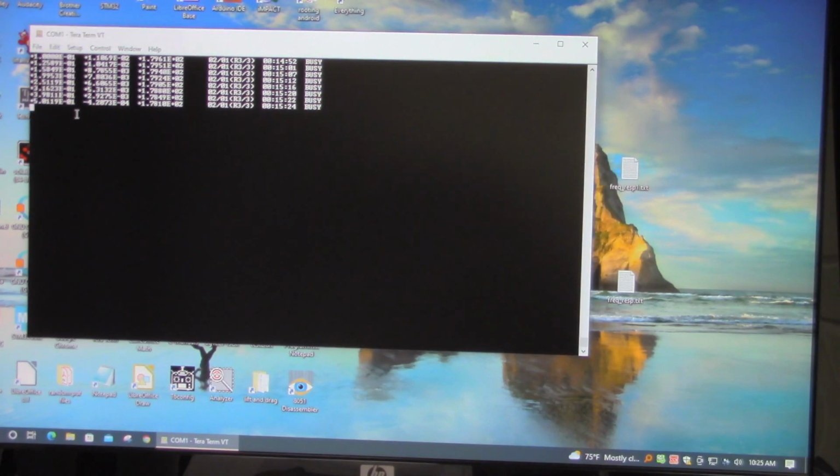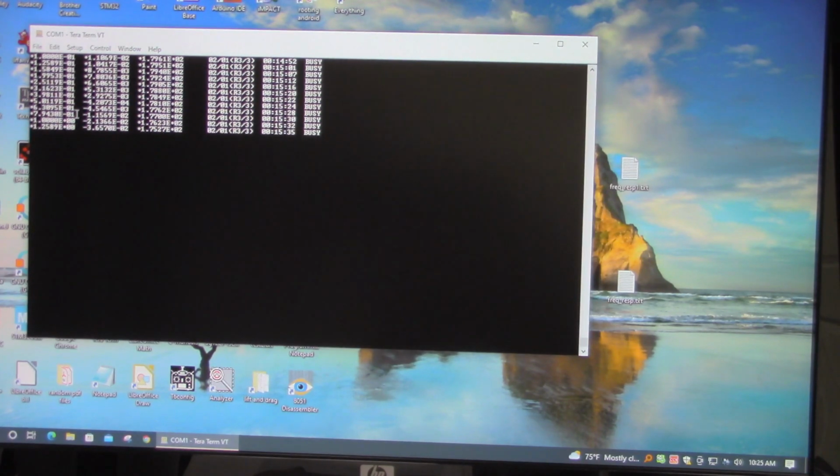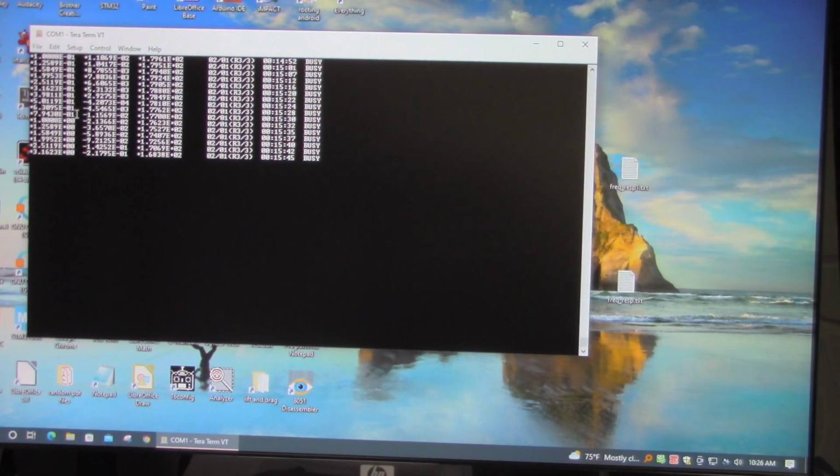I found that 10 points per decade is pretty good. If you want tighter resolution, yeah, you can do say 20. And so now it's running faster. It's going to do one every 2 seconds because I set that integration time to 2. But if it takes longer than 1 cycle, then it's going to take the time to do the 1 cycle. So say for the 0.1 hertz, it's going to take at least 10 seconds for it to analyze it.